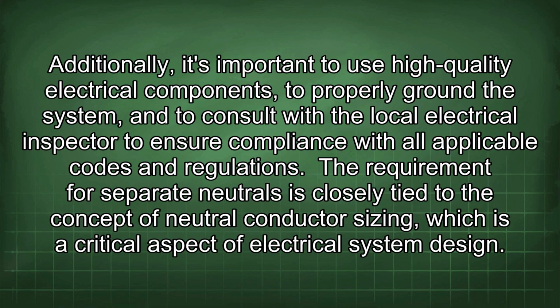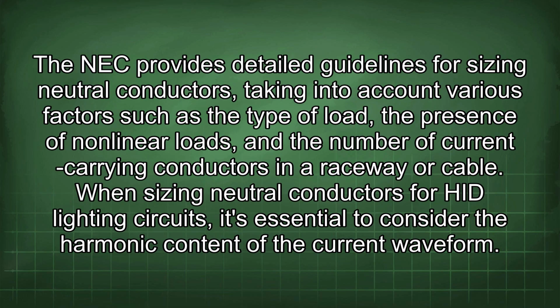Additionally, it's important to use high-quality electrical components, to properly ground the system, and to consult with the local electrical inspector to ensure compliance with all applicable codes and regulations. The requirement for separate neutrals is closely tied to the concept of neutral conductor sizing, which is a critical aspect of electrical system design. The NEC provides detailed guidelines for sizing neutral conductors, taking into account various factors such as the type of load, the presence of nonlinear loads, and the number of current-carrying conductors in a raceway or cable.